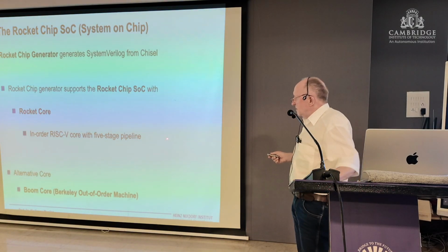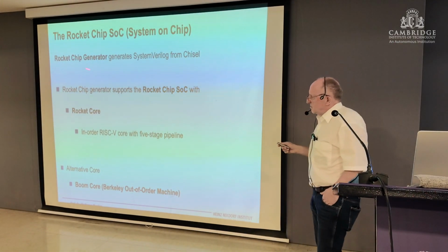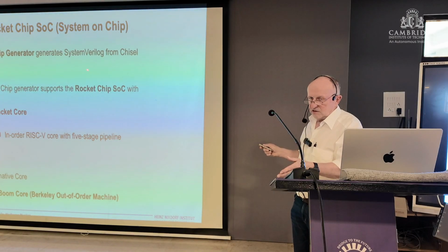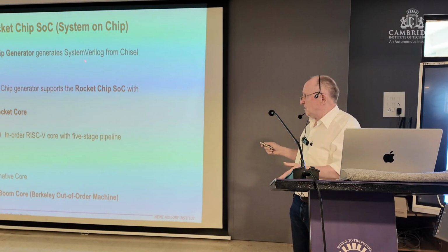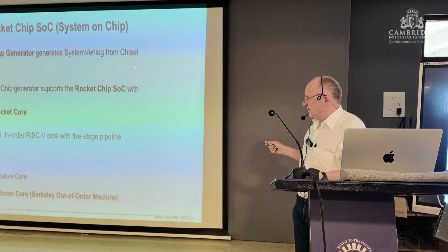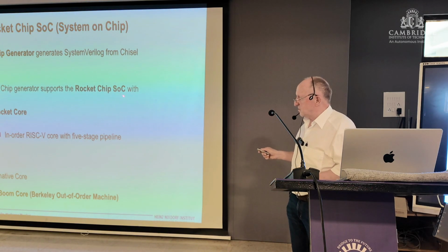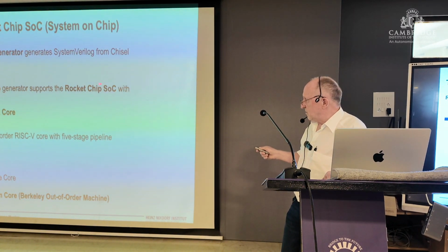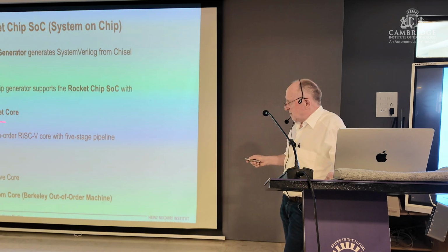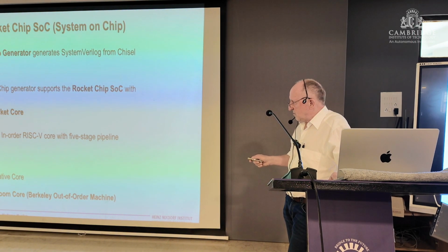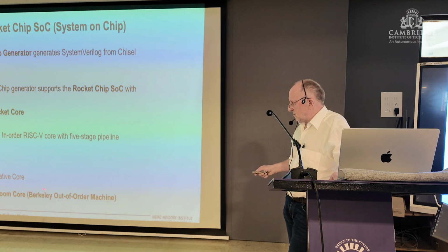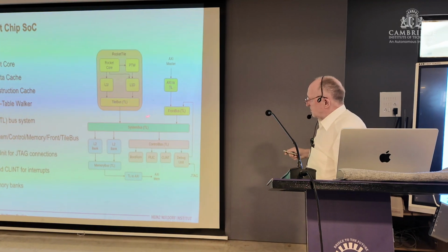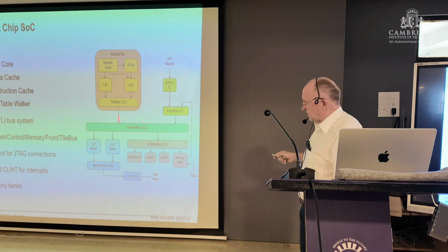In this context, Rocket Chip Generator is a tool which generates, as I showed you at the beginning, SystemVerilog from Chisel. It supports the so-called Rocket Chip SoC, which stands for System on a Chip. The Rocket Chip SoC currently has the Rocket core, or you can alternatively use another RISC-V core. So what is it about? This shows the SoC structure.